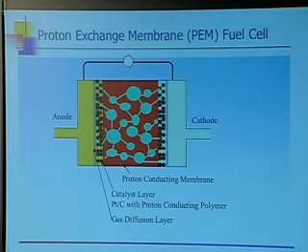We can take materials like zirconia and variations on that theme, and they will conduct oxygen as O2 minus nominally as an electrolyte at much more elevated temperature. The lowest temperature you can run those at is somewhere around 700 degrees C, and you'll quite often find those running at 1,000 degrees C.